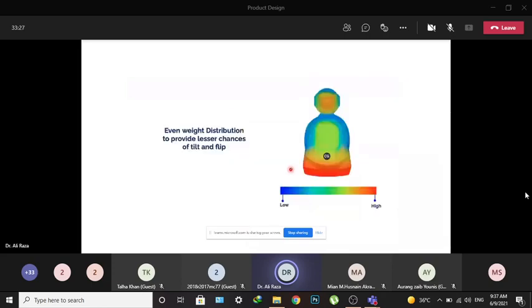As you can recall, the guys who were present last time, the center of gravity was also an important aspect. So there was one feature in the initial phases that was discussed, asking the robot to have a tilt forward or backward kind of arrangement. But after quite a lot of deliberations, it was identified that it is going to force the robot's center of gravity to come out of the envelope, and it is going to eventually, possibly, make the robot unstable.